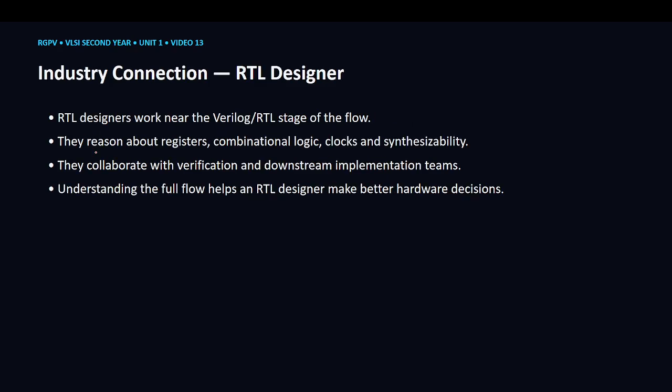Now connect this to a real career. An RTL designer works close to the Verilog RTL stage. They reason about registers, combinational logic, clocks, synthesizability, and reset behavior. They also work with verification and downstream implementation teams. This is why learning Verilog as just syntax is not enough. You need to understand the hardware and the flow around the RTL.